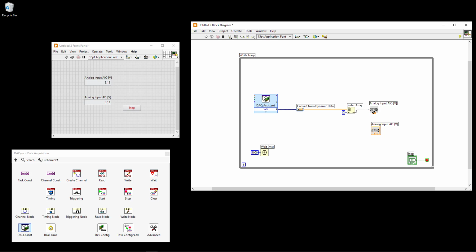And the output here will go to this one, and in order to also connect this one, I just need to drag it, and then here create type 1, and then this output here will go to this one like this. So this picks the first or a 0 element in the array, and this one picks the next element in the array. And then this will become analog input channel number 0, and this will become analog input channel number 1.